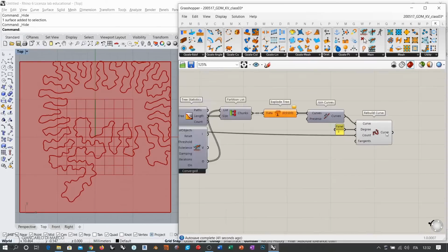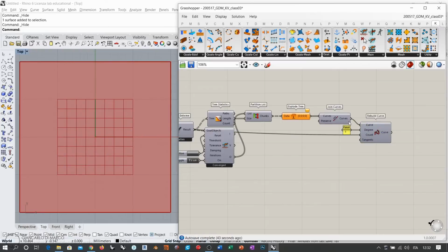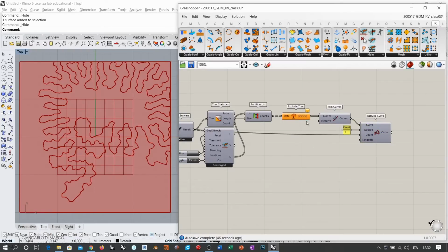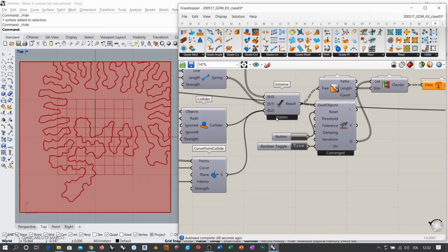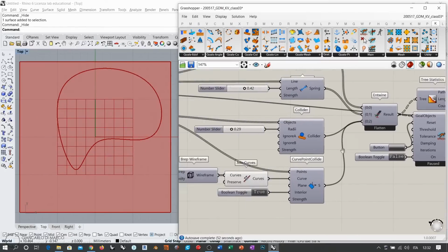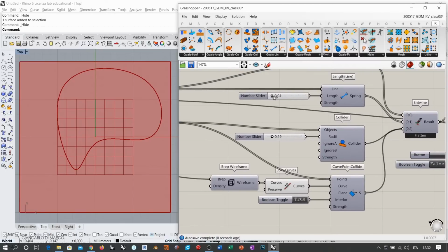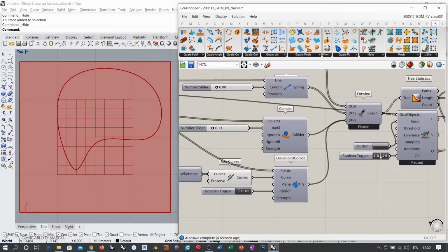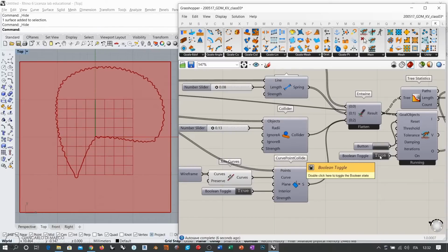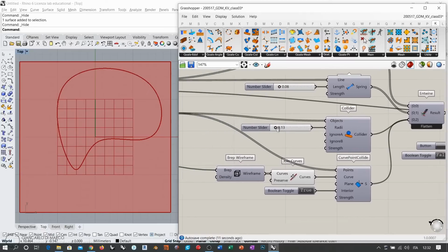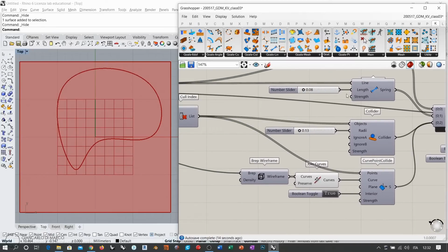Now, instead of doing this, I'm going to go back to the original preview. We still have the simulation running, so I'm going to stop it right now and reset it, and go back to our initial values, which were more or less 0.08 and 0.11, it shouldn't affect the simulation too much. So let's double check that everything works fine. Yeah, no self-intersection. So what we can do in this case is basically smoothen this line.